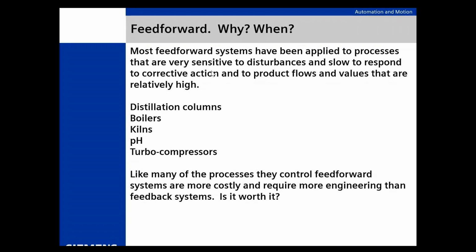Right here. Those are common applications of feed forward. Now, people talk about, it says like a kiln there. You go to a paper mill and they've got a lime kiln. Well, what are they doing? They're reclaiming the lime, burning it without burning it up, and reusing that lime. Well, the problem with that loop is when the lime goes in the kiln, it doesn't come out for 4 hours. So any adjustment I make, I'm not going to know whether it went up or down or whether I did bad or good for 4 hours.